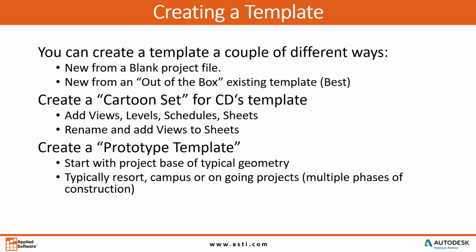But understanding the two basic ways of creating templates: you can start from scratch, or you can start with the out-of-the-box templates that Revit provides. And that's really the best way that I've seen for most companies taking on Revit and implementing it, doing a phased approach. Don't try to start from scratch. Start from at least a good starting point with the out-of-the-box templates and then build off of it.